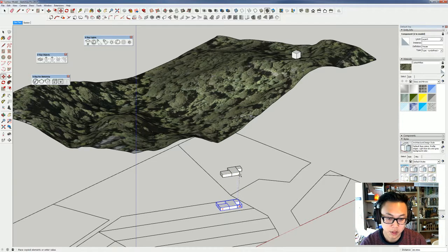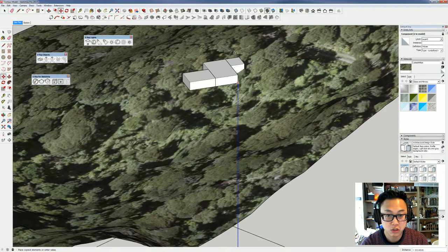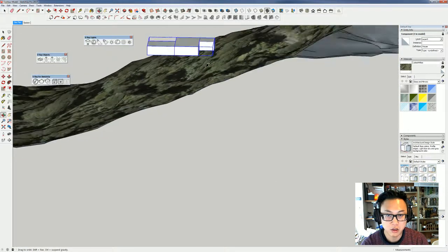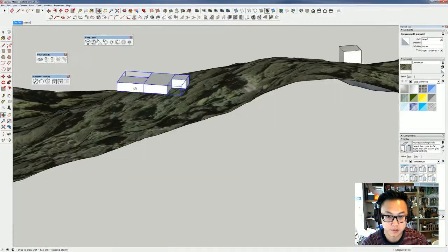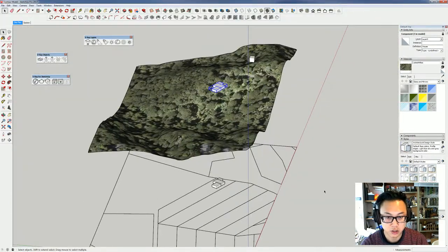maybe we can just create another copy, because like I said, when I edit components, it will be reflected on all of them. So now I'm just gonna move it so it's on the side. So I'm just gonna move it up, and because I want it to be locked to that Z axis, I'm just gonna press the arrow key, the top one. So now it's gonna be locked. So that's the arrow key on your keyboard, and I'm just gonna make sure it's a bit above the contour side, and I'll just show you.